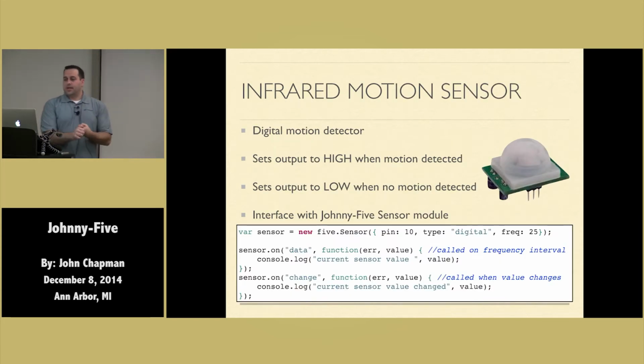All right, infrared motion sensors, right? That's that little bulb thing on the right, and you can see it around Mickey's neck there. And basically there's a couple different ways this works, but the way we have it set up to work is whenever it detects that there's motion, it'll set the trigger to high, saying I've detected that there's motion in front of me. There's potentiometers on the back that allow you to control the sensitivity, but that's basically all it's doing. It says I have motion or no, I don't have motion.